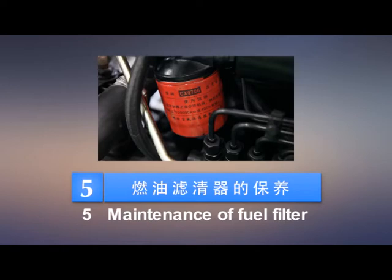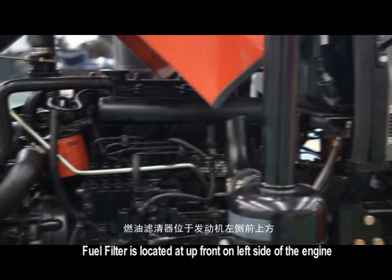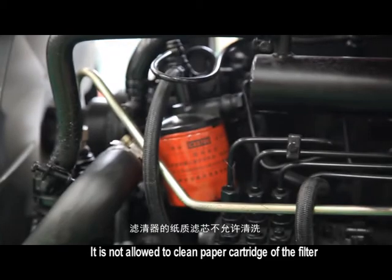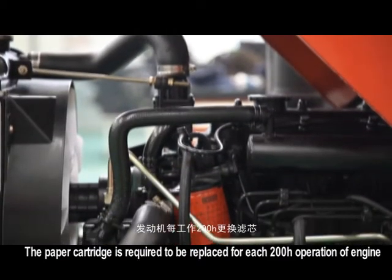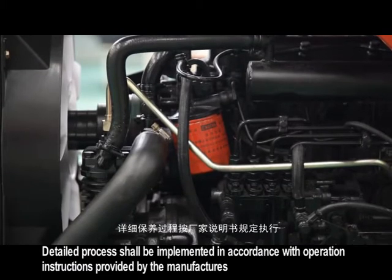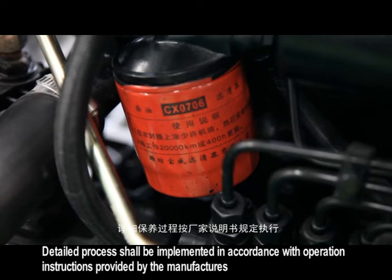5. Maintenance of fuel filter. Fuel filter is located at up front on left side of the engine. It is not allowed to clean paper cartridge of the filter. The paper cartridge is required to be replaced for each 200H operation of engine. Detailed process shall be implemented in accordance with operation instructions provided by the manufacturers.